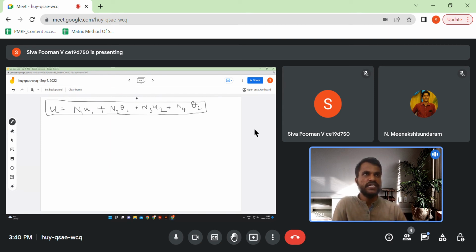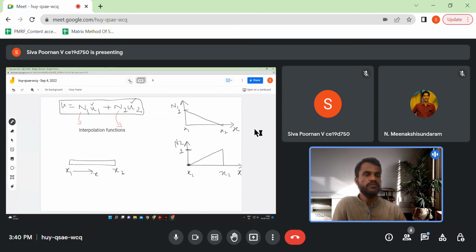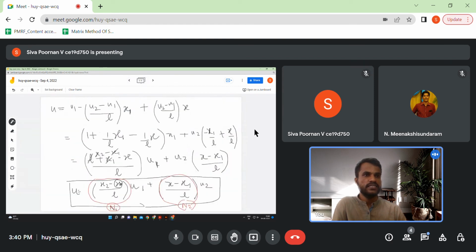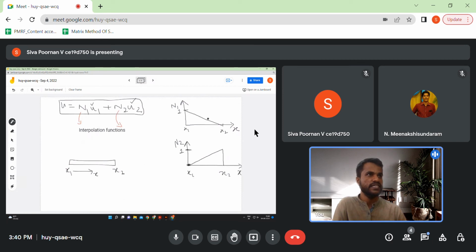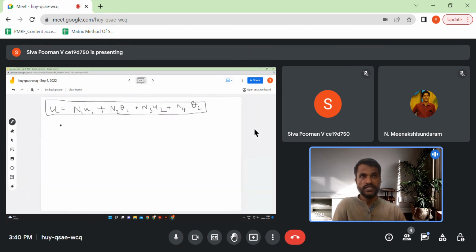Actually it will not be a linear function. In the previous truss problem we observed that N1 and N2 just have a linear variation with x, therefore they were varying linearly with x, their diagrams are linear. But here what we would observe is that there will be a cubic function of x. Therefore, they will vary cubically with x. Okay. So if you want to draw their variation with x, how do you find out? You can actually guess it.